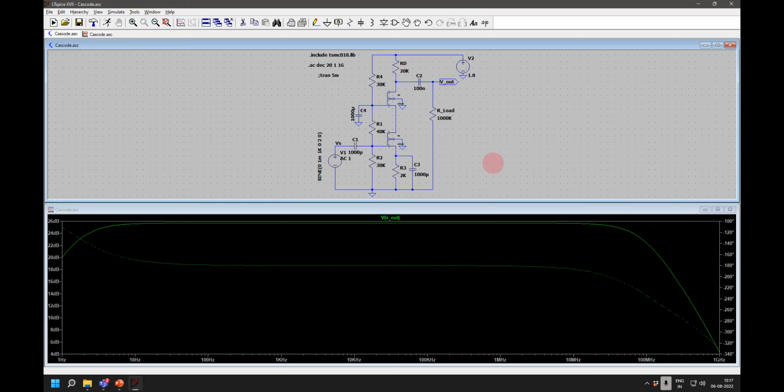We cater for both resistance and capacitance. If you are driving another CMOS amplifier, it will be a gate capacitance. But if somebody uses a resistor there to bias the network, even that resistance becomes a load. For analog circuits there is no fixed requirement; every circuit will have a different requirement, so accordingly it will change.